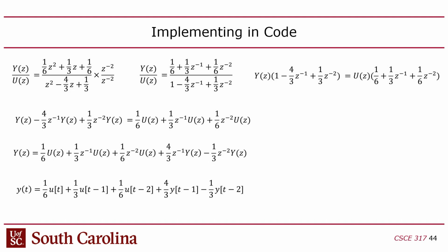Now you might say, why? Because if they're positive, you'd have to know the future. Z to the negative power means past. So really, I want a controller that calculates the output as a function of previous samples. If you can get into that form, you can build a C implementation of this.